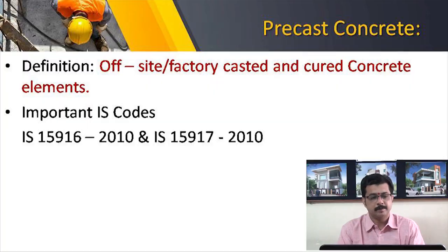Now, this technology is also governed by few specifications. These are the specifications which are given by IS 15916-2010 and IS 15917-2010. These are the IS codes which deal with the prefabrication process and erection of these precast elements.